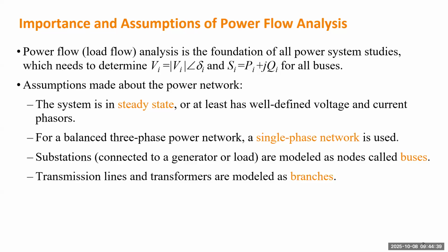If you remember, for the transmission line models, we can convert all lines, no matter whether it's a short line, medium line, or long line, into a pi model. For the short line and medium line, when we take the pi model, it can be accurate, so the impedance will tell the actual impedance. For a short line, we can even ignore the capacitance to the ground and only keep a single impedance. But when we take the pi model for a long line, you need to convert the impedance Z into Z prime, and the Y into Y prime. Then you can use the pi model.